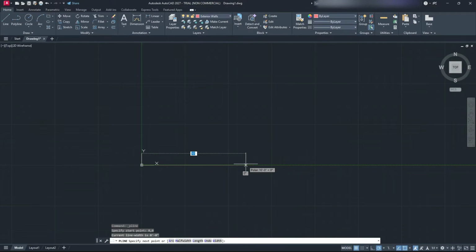Then I can drag it to about 10. The distance is highlighted. We're going to type in 10 and press the key for feet. That's the key beside the enter key. You're just going to press that for the foot. If you need to do inches, then you hold shift and press that key as well to give you the 2. So feet is 1 and inches is 2. And those of you who are metric, you just type in 100 or whatever your equivalency would be.